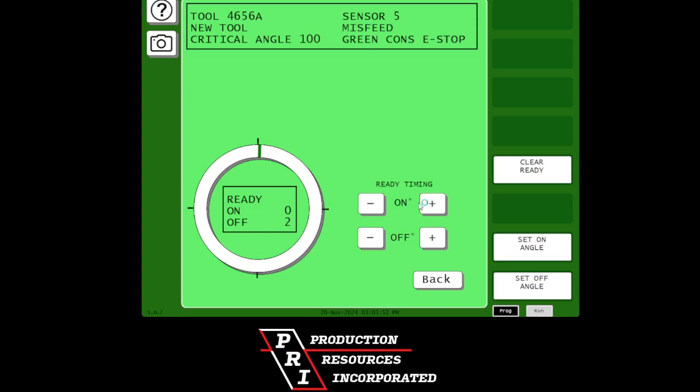The green sensor being a cyclic event, we expect the sensor to activate every stroke. It is critical that this event occurs when it is expected. We know from experience that our feed should be fed up by a certain degree angle, and it should maintain in place after the feed is completed.